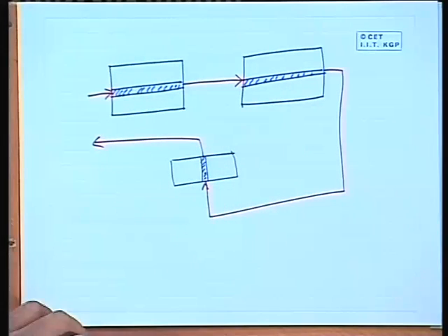This helps you in saving time in testing, in a sense that, see, the test generation and fault simulation algorithms, they are pretty complex. They take time which is more than of the order of n square, where n is the number of gates. So if you can break the whole circuit into a number of smaller circuit and apply these to the smaller sub circuits, then the total time that you require will be much less in general. Okay. So that is why this kind of a divide and conquer approach helps in reducing the total time that you need for testing. Okay.